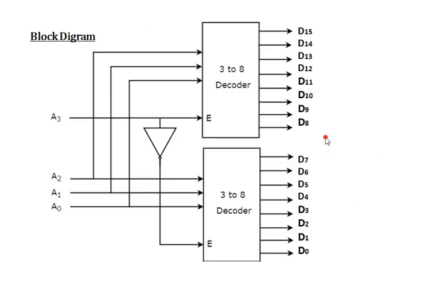Next, observe, this is the block diagram. Here I have taken, this is my first 3-to-8 decoder. This is my second decoder circuit. We know a 3-to-8 decoder has 3 inputs, so I have taken 3 inputs, either 0, 0, 0 or up to the last one, 1 1 1. We know 3 zeros to 3 ones, total 8 values. So 3 inputs initially I have considered.